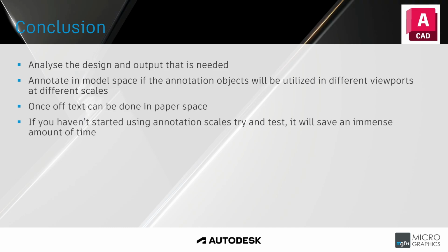The dimension text is connected to that line. If you do it in your viewport, you'll notice that if I move my viewport or change my scale, it doesn't move automatically, it leaves the dimension behind. I can't remember the command now, but there's a command to reattach all your dimensions.